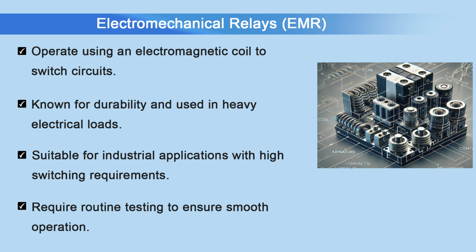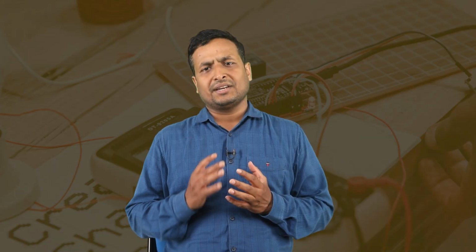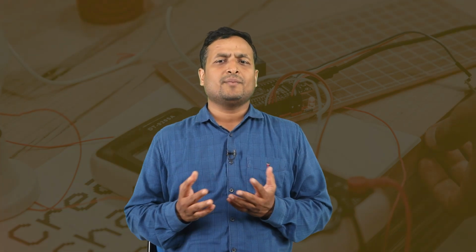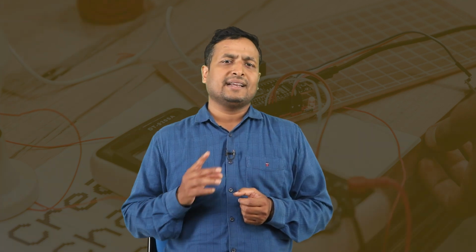or close. These relays are widely used in industrial control systems, automotive electronics and home appliances. They are preferred in applications where simplicity, reliability and cost effectiveness are prioritized. So, what are the testing considerations here? These relays require functional testing to ensure that the mechanical movement of the contacts is smooth and free from wear and tear. Timing tests are also crucial to verify that the relay responds within the required time frame or not.